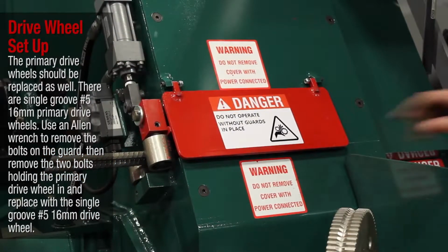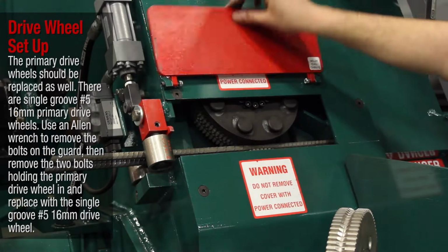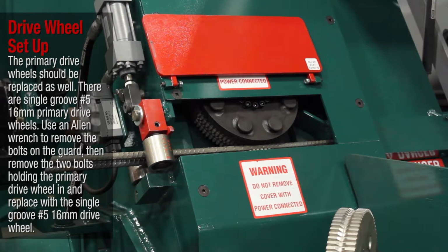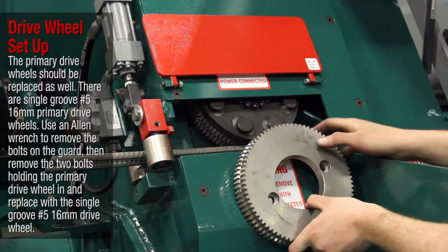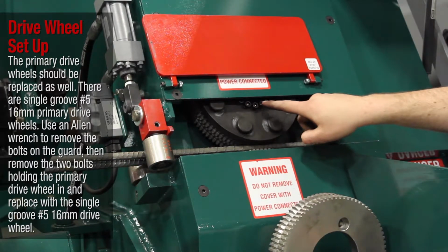The primary drive wheels should be replaced as well. There are single groove number 5 16mm primary drive wheels. Use an Allen wrench to remove the bolts on the guard. Then remove the 2 bolts holding the primary drive wheel in and replace with the single groove number 5 16mm drive wheel.